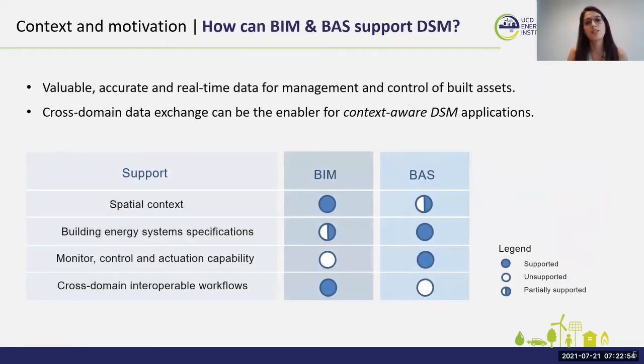How can BIM and BAS support that? The integration between BIM and BAS can provide valuable, accurate, and real-time data for the management and control of the building assets, enabling what we call context-aware demand-side management, based not only on the grid signals and market signals, but also on the current and real-time operation of the building, all the context that involves the building, also location of the equipment, schedules, comfort levels.